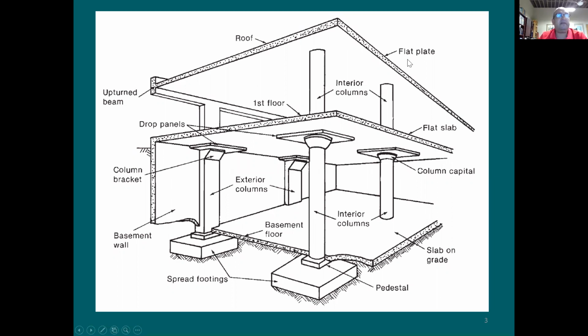So a flat plate can have maybe a ridge beam, like a marginal beam, something in the perimeter that is going to be accepted, and you still call it flat plate. The good thing about this system is that you don't see any beam dropping down. So if there is no full ceiling, like a T-bar ceiling, it's going to look beautiful, right? Because you don't see anything there, unless you have pipelines or light fixtures and you want them to be exposed.